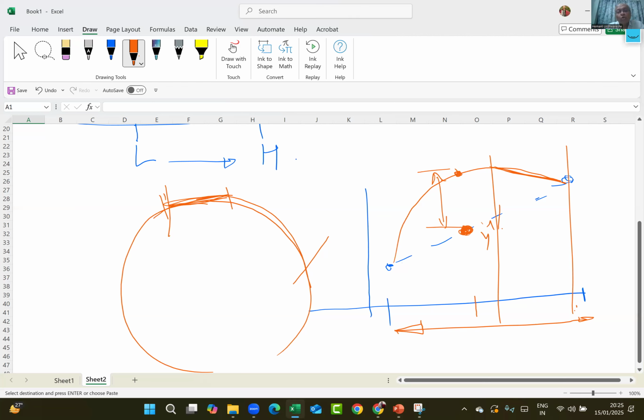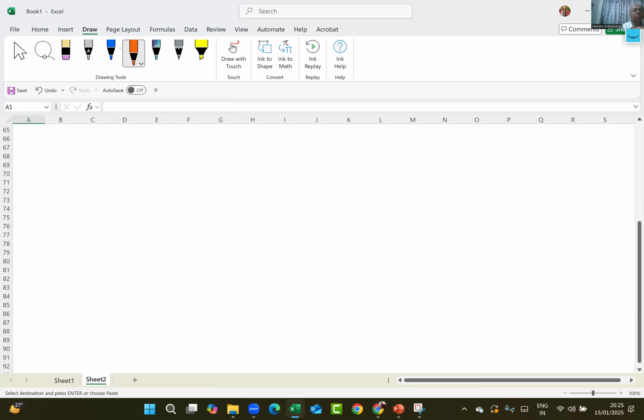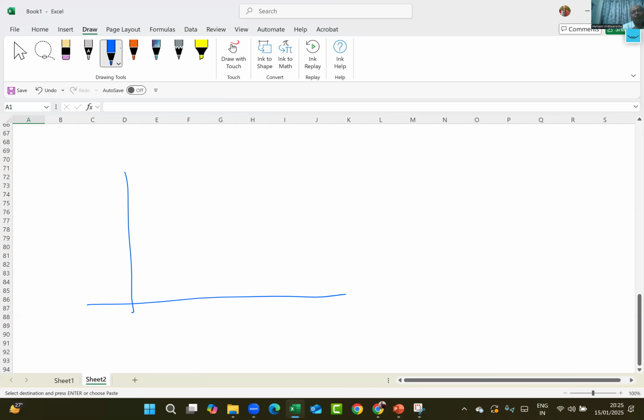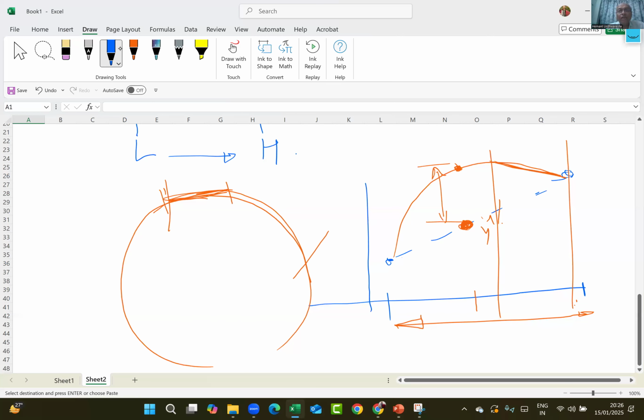Number two, if it is too small a difference, then you got other problem. Let us say you set the difference very small. Now your effect is, let us say, like this. The effect that you are getting is so small that it may not be accurately measured by your measurement system, and you may get a measurement error which interferes with your effect calculations. So very small difference between the levels can create measurement issues. Very large difference can create non-linearity problems. What is the solution? Choose level differences which are not very large or very small.